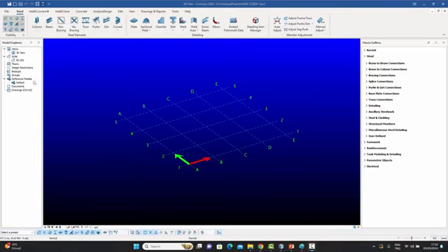The first thing I want to say is that these reference models are very similar to the groups you're already familiar with. Just like you can create as many groups as you want under the Groups tab, you can create as many sections as you want under your reference models, and then you can import as many models as you want under each subgroup. You're provided with one subgroup to begin with, which is called default. You can right click there and say add new group, and create groups under that as well. But let's not go into that.